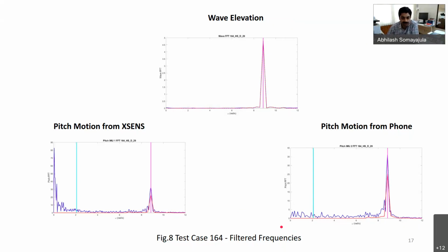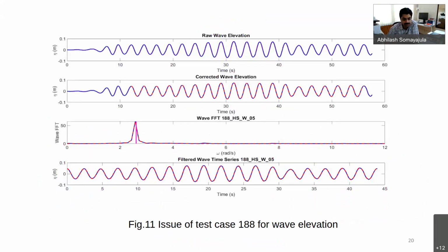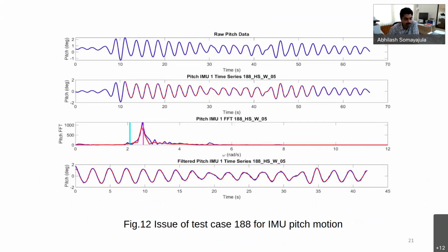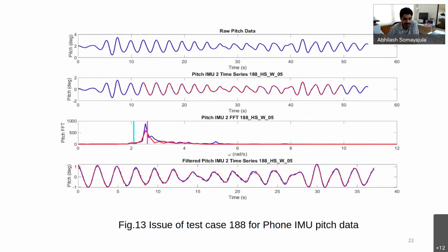When we were doing the RAO tests, by any chance, if we were exciting roll, then we were not purely measuring linear motions, and some funny behavior might be coming in. I wanted to check that at that frequency. That's why that line is there. So that corresponds to the roll natural frequency. Okay, sir.